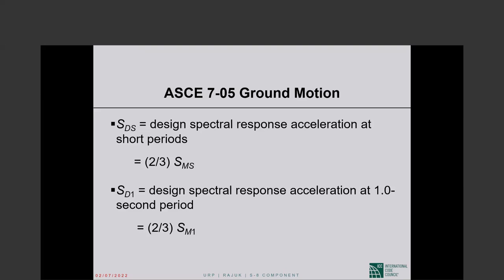So we believe that buildings designed by the 1973 UBC or subsequent building codes are unlikely to collapse on us until earthquake ground motion equals and then exceeds 1.5 times the design earthquake ground motion of those days, which had a 90% probability of exceedance in 50 years.